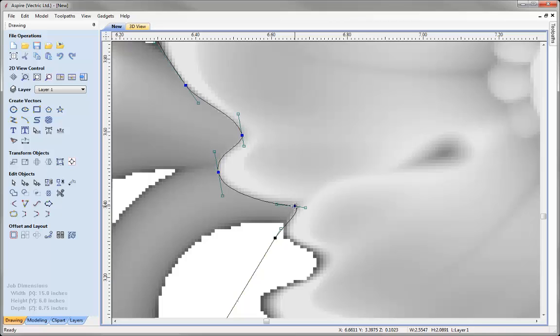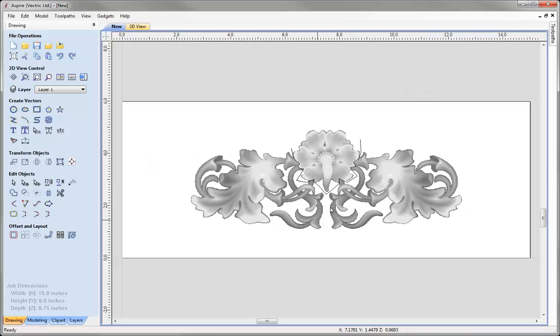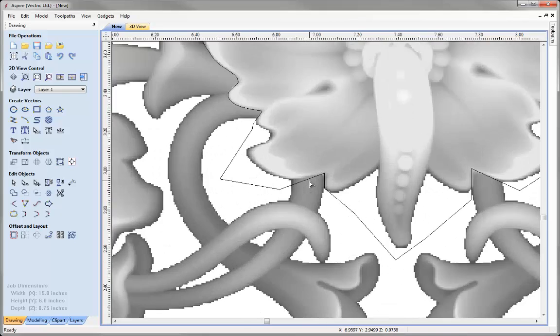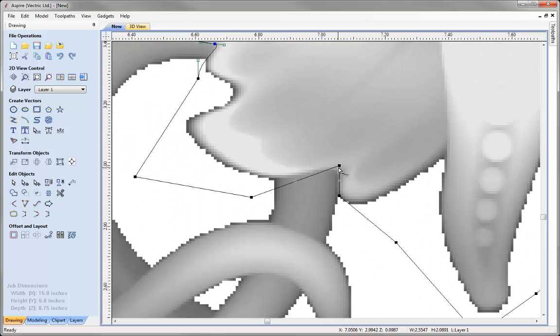So this is going to take me a couple of minutes here. As I say, it's really worth me taking the time to make sure that this vector follows the flow and the shape. Can hit F to fit that in and then zoom in on the next area. Here I'm going to hit S on the keyboard to smooth that, and then we'll just make that a bit of a sharper line. We'll smooth that one as well. Just drag this up. So I just want to get that flowing in there. In fact, we may even delete that.